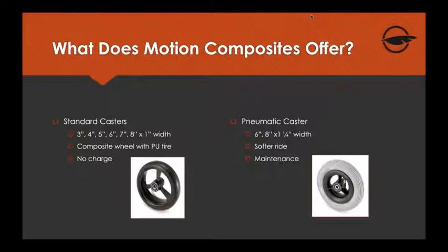The tubes hold very little air compared to a rear tire, so it bleeds out very quickly. Over time, if you have to inflate your rear wheels every 2 to 3 weeks, anticipate about every week with a caster. So it's maintenance intensive, and that valve stem can be kind of hard to get at too. So you've got to have pretty strong fingers and good dexterity to get in to do that.